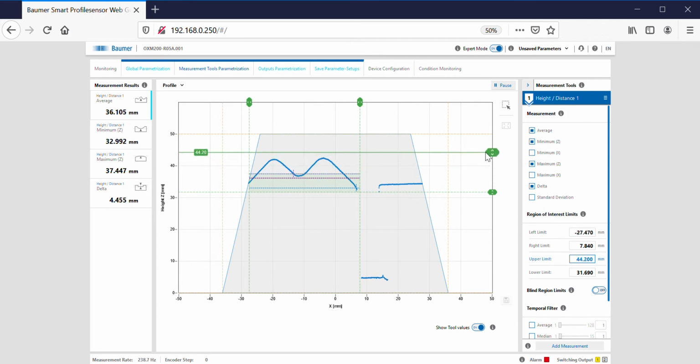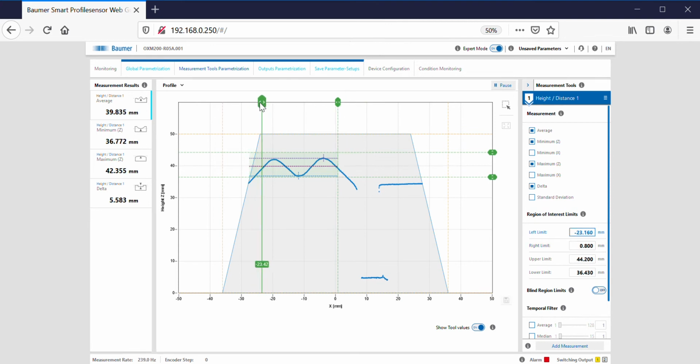But if I choose all the way to the top of those peaks, say I wanted to know the difference between this area here. For example, if I do something like that, it's choosing the bottom here to the peak here, and that's my delta in millimeters. So you can see you can do some nice little features for profile measurement.